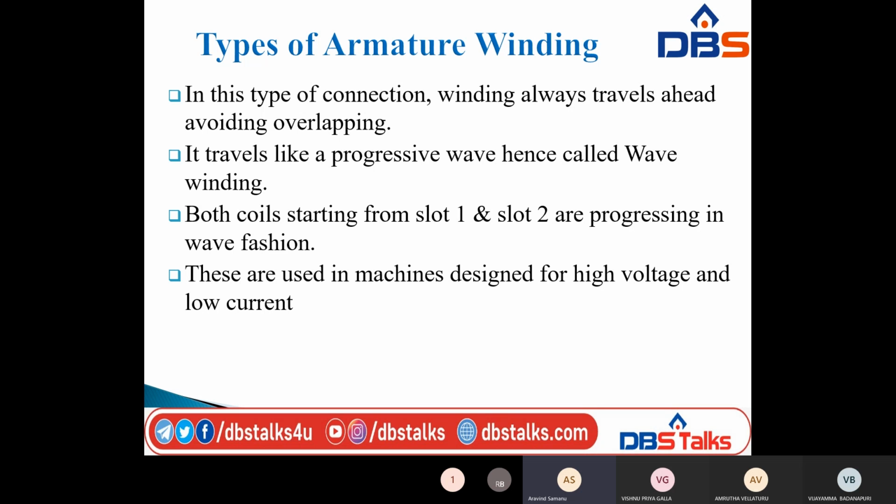Okay. So in the previous case, what happened? The lap winding is designed for low voltage and high current. But this type of wave winding is designed for high voltage and low current.